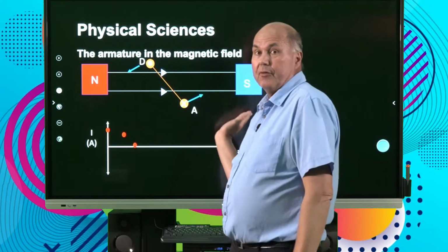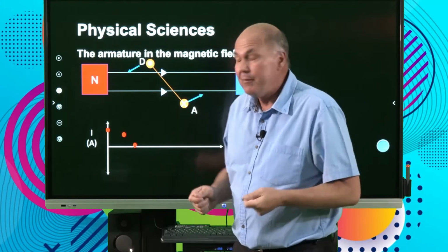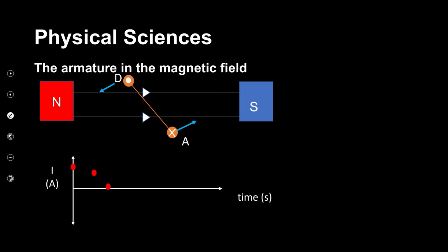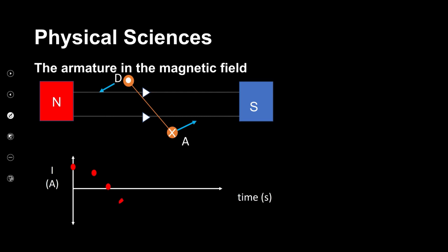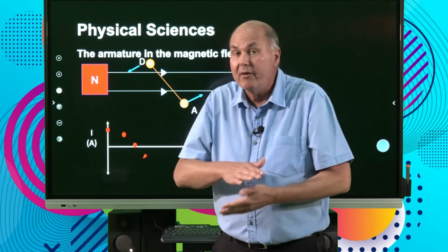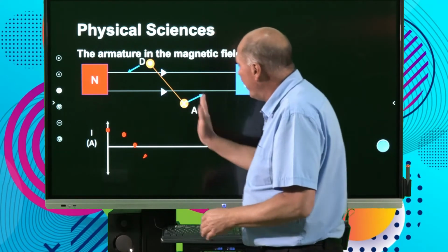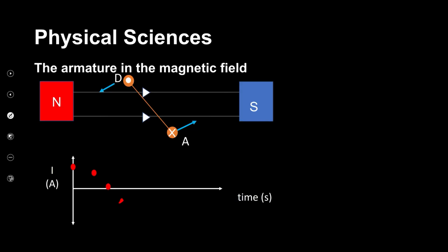So it's gone through this process. This can happen very quickly. But what do you think is happening now? Well, the current in D was in and now it's out, so it must be a small negative value. So at that point, there is a current going in, it's not the maximum yet, there's still an angle between the coil and the field lines, the area isn't perpendicular, so we're recognizing that the cos theta here is a value that is not 0.